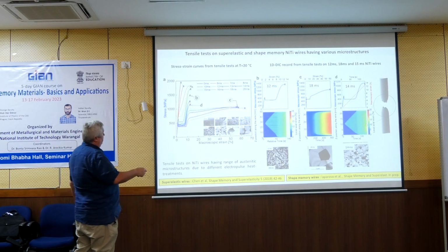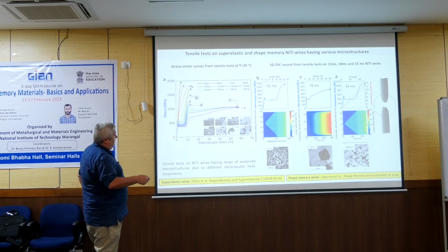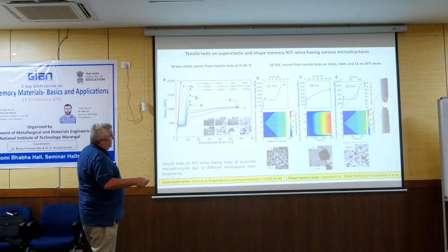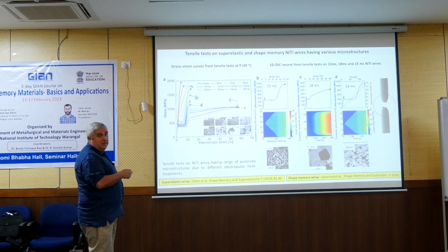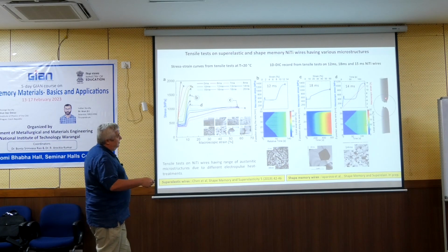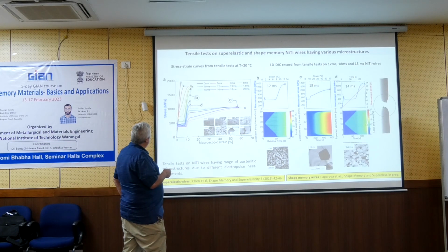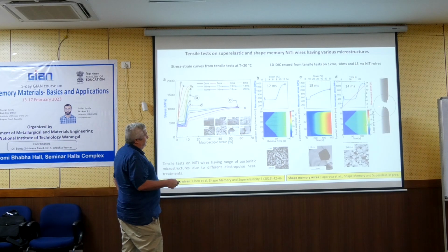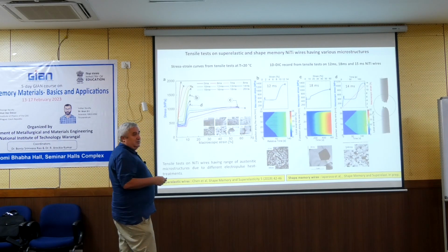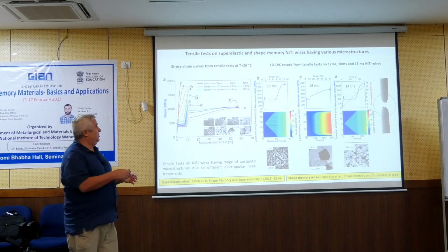because here we knew it was probably too dense. And while doing this research, we found that in fact this brittle fracture over here is not brittle. If we look at the wire of 14 milliseconds, this is this D, there is a neck. So in fact the material is very plastic. This is not a brittle fracture.